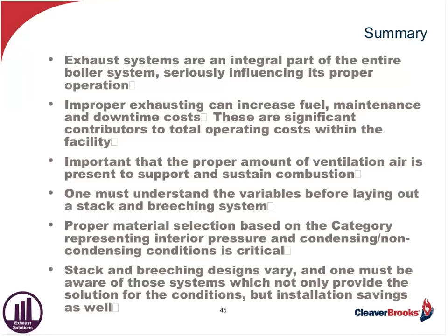In that particular situation, you could also get into an oversized condition where maybe those dampers that we talked about, the automatic damper, would be sensing the excessive negative pull within the breeching and stack, and as a result would begin to pinch off and increase the resistance. Because with these, what you're looking at is either zero draft at the vent stub or slightly negative. That's the ideal condition that Chuck was actually driving at when he was going through those two scenarios.